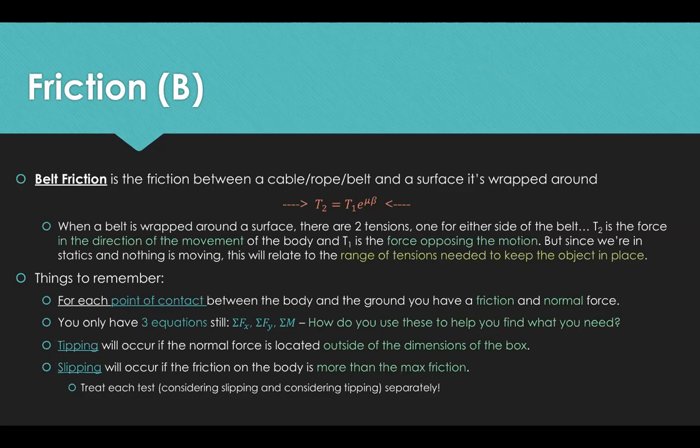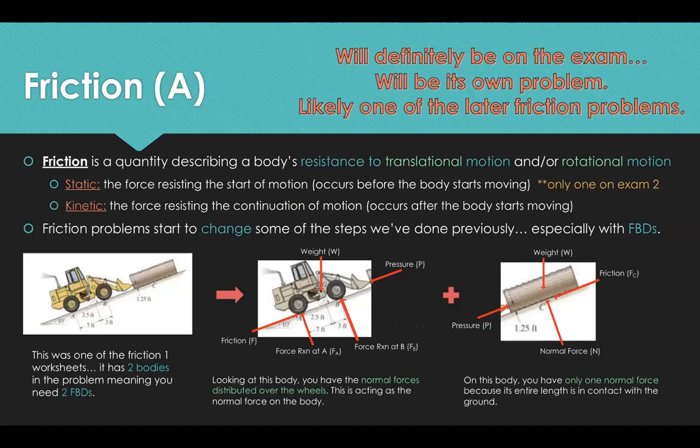And the way to calculate that is by finding the position of the normal force on that box, right? So if I'm going to see if this applied force is causing the box to rotate, I can choose to evaluate either this corner, assuming the box is going to fall down the hill this way, or I can look at this corner, assuming that my applied force is going to cause this body to rotate about here.